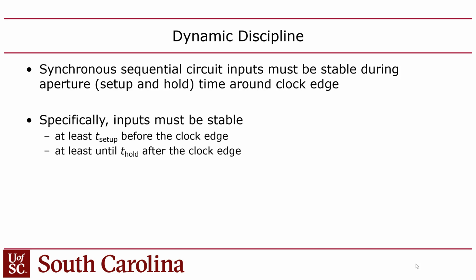A lot of people think, well, there are a lot of expensive problems that the CAD tools have to solve. One is parsing your Verilog and converting it to gates, but then you have to take those gates and map them onto LUTs. Then you have to figure out which logical LUTs you're going to map onto which physical LUTs. And then you have to make connections between them in the routing fabric. And then you have to run this timing analysis and tell the user how fast the circuit can run.